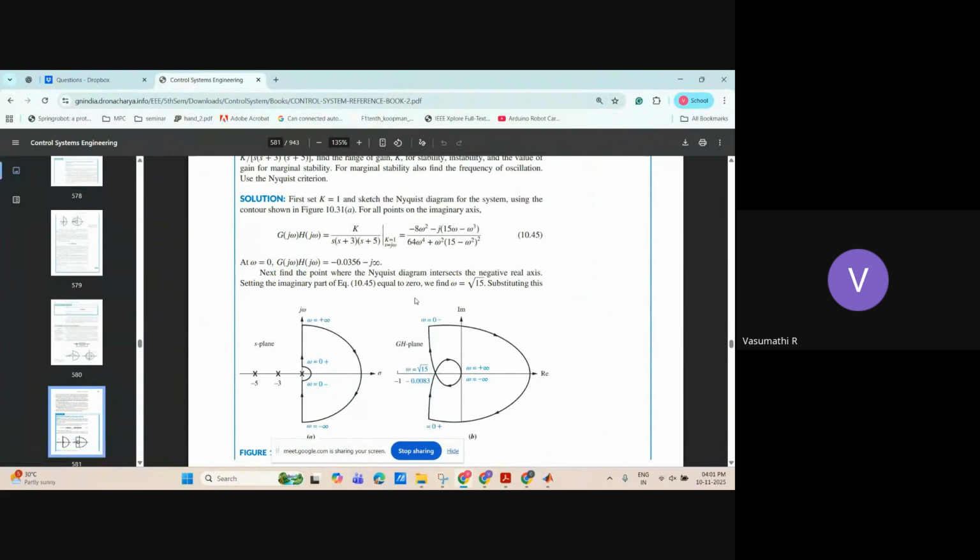So I'm considering unity feedback. How to write a closed loop system? feedback(G1, 1). So this will consider a unity negative feedback and write the closed loop transfer function. I will show the open loop and closed loop transfer functions. So this is G1, and C11 is the closed loop transfer function. Here if you see, this is 1 by s cubed plus 8s squared plus 15s, right? Here it is s cubed plus 8s squared plus 15s plus 1. It is added, it's a closed loop transfer function.